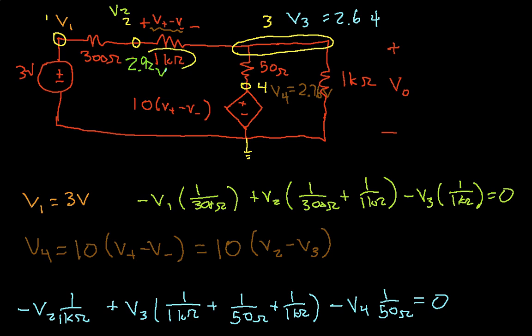But as we increase the input resistance, which is 1 kΩ, and as we increase the gain, so we change the input resistance from 1 kΩ to 1 MΩ, for example, and increase the gain to 10,000, then this output voltage would get very, very close to 3 volts. So for a real op-amp, again, this output voltage would be very close to 3 volts.